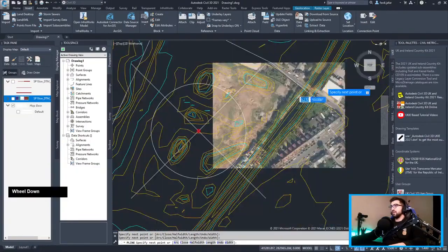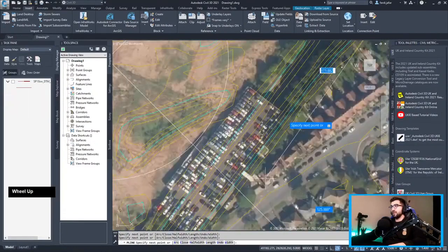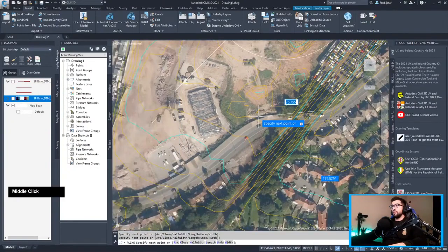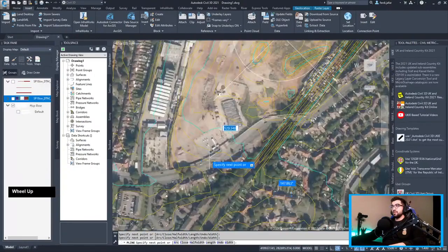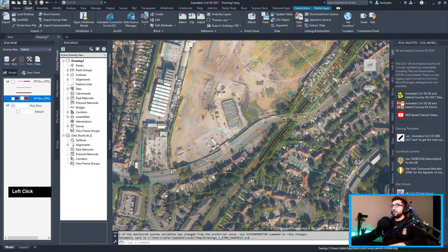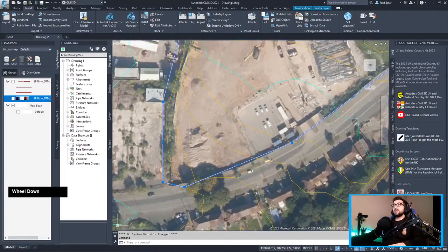Actually, let's pull the, what seems like a river. Yeah, or a brook, not sure what I would call it. But what I would suggest is to offset the boundary outside. The reason we're going to offset the boundary outside is because, let's say you want to draw sections and you want to see what happens beyond the boundary. Don't cut your information there, allow for a tiny bit, like 10 meters. And let's say that is our boundary now.